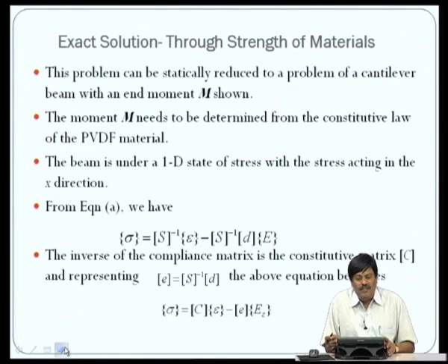Before doing that, we can derive the exact solution to this using the strength of materials approach. As I said, the problem can be statically reduced to a problem of a cantilever beam with an end moment M as shown in the figure. The moment M needs to be determined from the constitutive law of the PVDF material. The beam is under the 1D state of stress with a stress acting in the x direction. So, we have simplified the problem considerably, so that we can go ahead and do a simple exact solution, and we will check this exact solution with our beam element formulation.